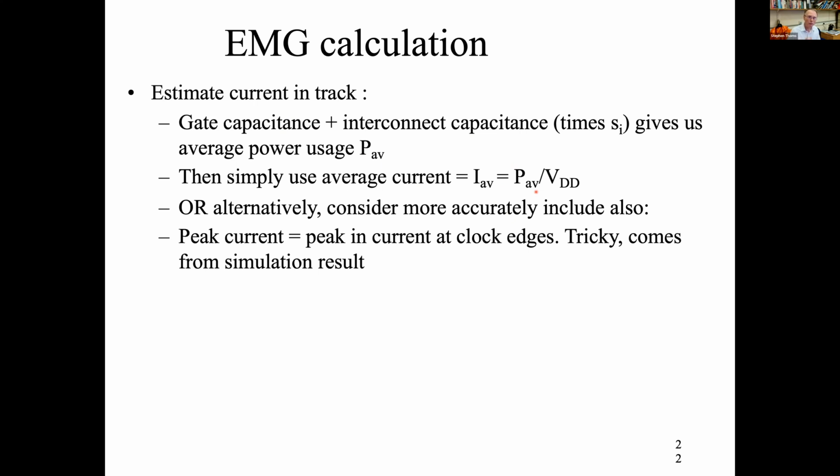Alternatively, and more accurately, we can start looking at peak currents. So for instance, at clock edges, the current's going to be much higher than anywhere else. So that's clearly an important thing to look at, but that is harder and needs some simulation.